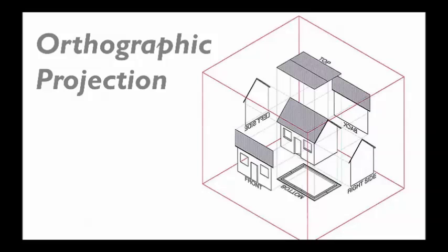But in the process of communicating how it's measured, what its accurate dimensions and measurements are going to be, we often take surfaces of that 3-dimensional building and project them out. So it's as if we're pulling or extracting out the sides, the bottom, the top, and then we make these flattened 2-dimensional images or drawings of the building.